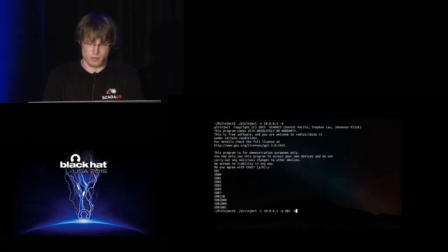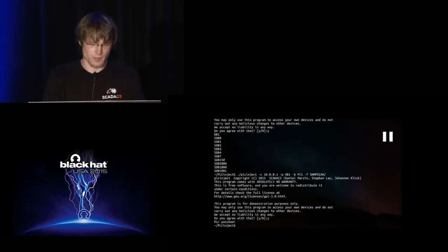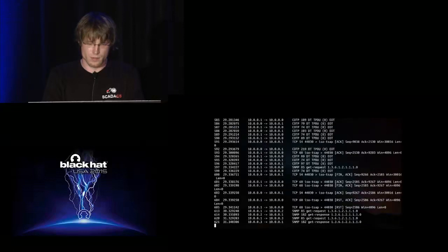Right, we patch OB1, insert a call to FC1, and provide a path to our malware. During this whole attack, we had a T-Shark instance running in the background, which we will see right now. T-Shark simply captures all traffic, all network packets on the network. And there we will see, after we injected the SNMP scanner, on the last 4 lines, that PLC1 immediately starts sending SNMP GET requests, and PLC2 and PLC3 respond to this request.